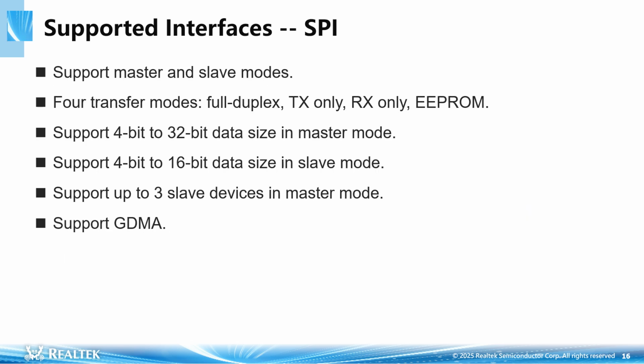SPI supports master and slave modes. Support 4 transfer modes: full duplex, TX only, RX only, EEPROM. Support 4-bit to 32-bit data size in master mode. Support 4-bit to 16-bit data size in slave mode. Support up to 3 slave devices in master mode. Support GDMA.